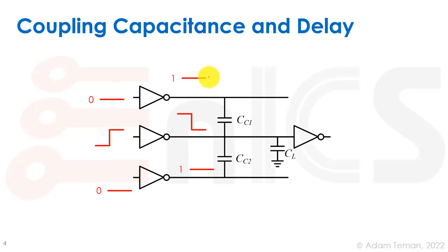It keeps a constant voltage at these two nodes, but the voltage over here changes. And that means that we had, for example, 0 volts on this capacitor and this capacitor before the change, and after the change we went up to a 1 volt difference over here and a 1 volt or a VDD here, VDD, let's say.